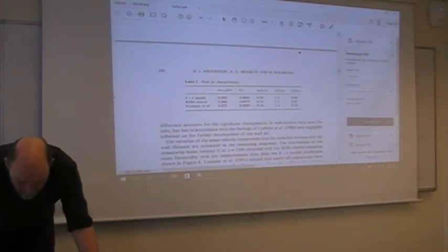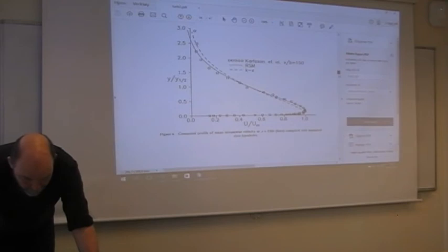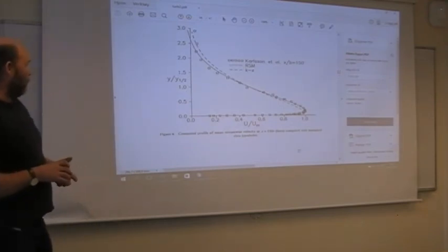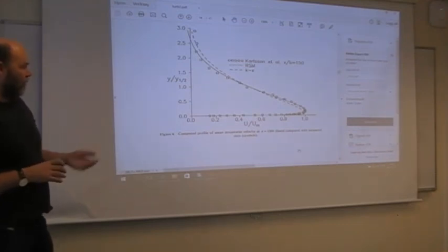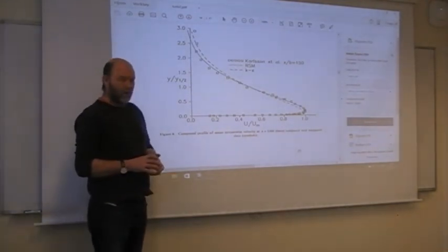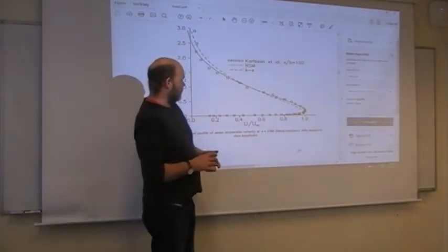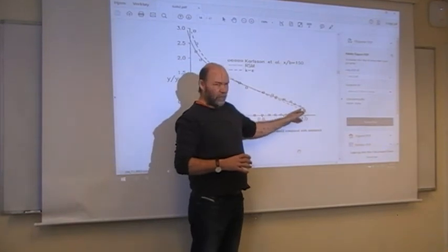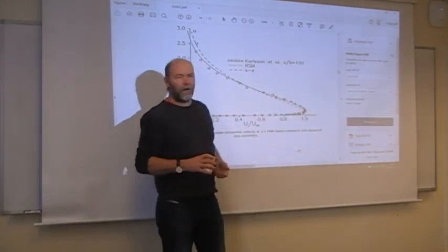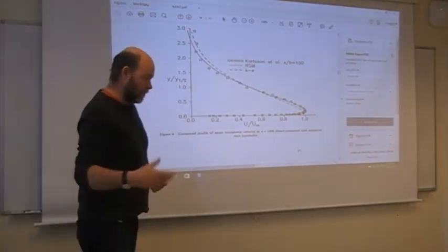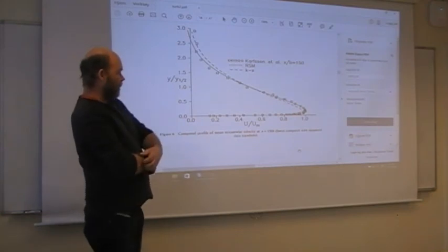Yeah, some characteristics, some data compared. You know, you can get this yourself if you like. So here the velocity profile again. The mean velocity is not that hard to get a decent value of. But it's a little dangerous because small differences here from what it should be will have a very large effect on higher order quantities like turbulent intensity, turbulent kinetic energy.